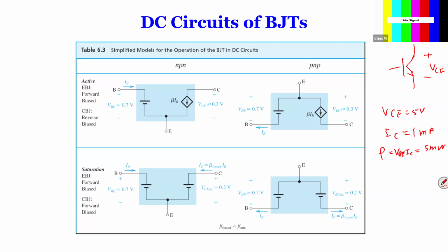So that's where it comes back to why MOSFET. With the MOSFET, the VGS can be as small as 0.1 volt or 0.2 volt. That's the advantage. And also current: the biasing current for BJTs is always in the milliamps. So in the ideal case, you can't put a million BJTs together to make something because there would be too much heat. But with MOSFETs you can do that, because a MOSFET operates in microamps.